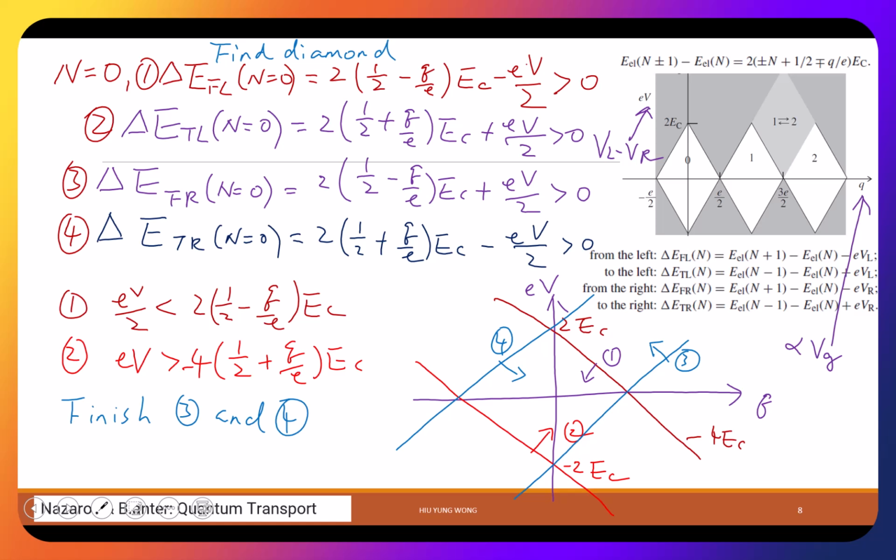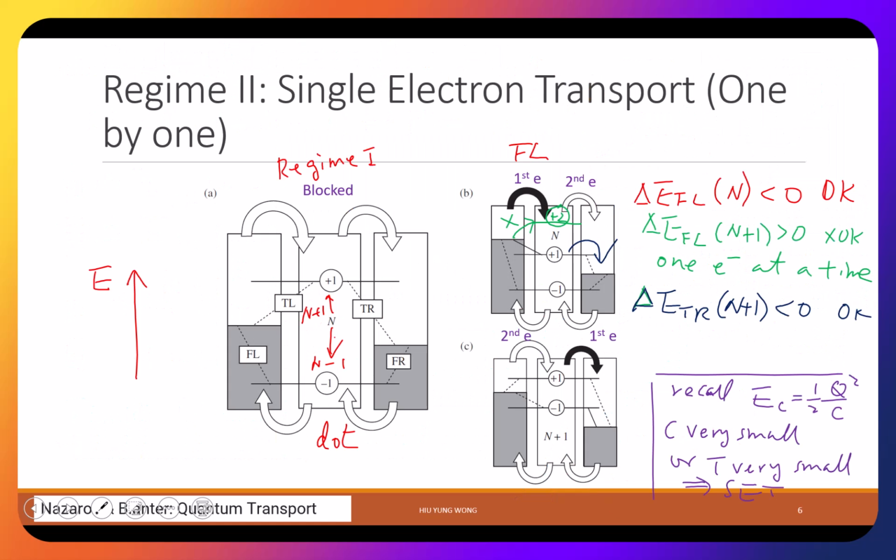First of all, here we never talk about the shape of your quantum dot. All we say is you have a dot with a certain capacitance, right? So what it cannot account for is, for example, the parasitic leakage, right? For example, it can leak to the gate, so there is a problem. Another is, for example, a photon can assist the tunneling. Then you will leave this single electron regime easily.